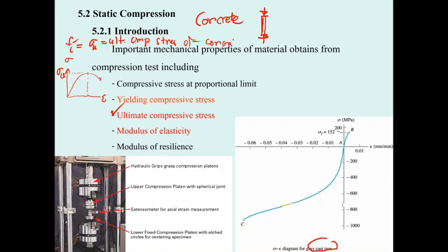You also need to specify this when you buy the concrete, especially ready mix concrete. You specify, I'm going to buy the concrete with the strength of 320 kilogram per square centimeter or 400 kilogram per square centimeter, and then you need to collect some concrete specimens in every 50 cubic meters, and then you test it and check it against what you really bought.